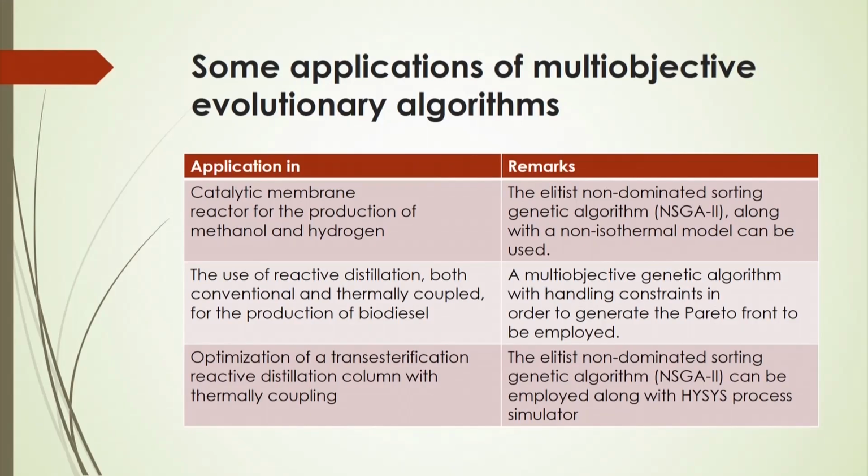Another application is the use of reactive distillation, where both conventional and thermally coupled systems are being used for the production of biodiesel. In that case, again, a multi-objective genetic algorithm with handling constraints is used in order to generate the Pareto front, that is, a set of optimal solutions that can be applied for the analysis of this reactive distillation.